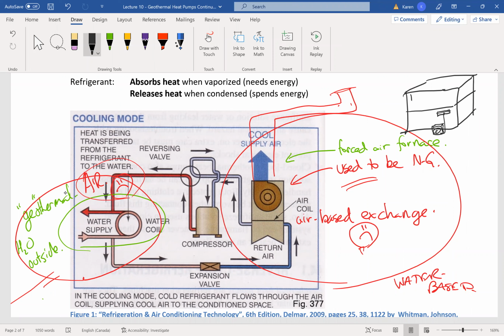So you're going to supplement all these rooms. The master bedroom is really big in these houses. I'm not insulting anybody who lives in a big house like that, but they are definitely grand. So there you go in that room, and then maybe you need to supplement in this big two-story windowed hallway or whatever, right? So this system is too small just because of those losses. It is electric, yes, because you're paying for this compressor. That's it. You're electric. You've eliminated fossil fuel. That's great, but it's too small for a lot of these systems.